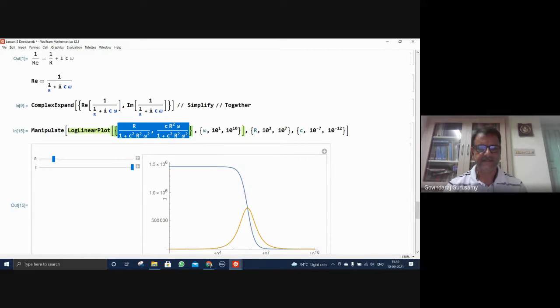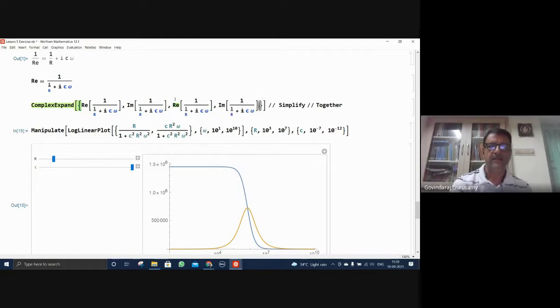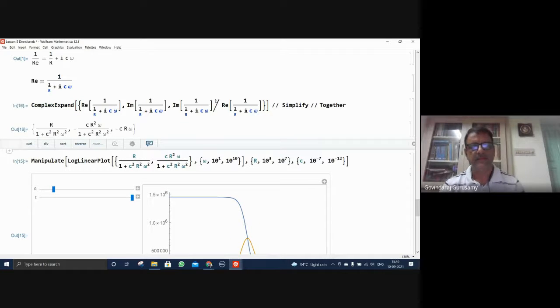What about the phase? And this is what your phase. I'm just showing you the phase. Imaginary part divided by real part. That is what your imaginary divided by real part. Minus CR omega. That is your tan phi. And inverse of that is going to be your phi magnitude. So we know the ABS value and the phi, and it can be plotted and it can be shown.